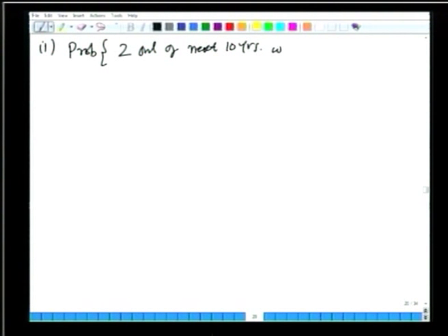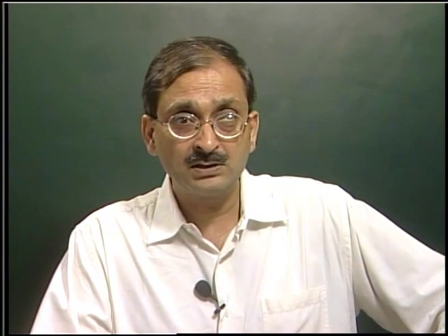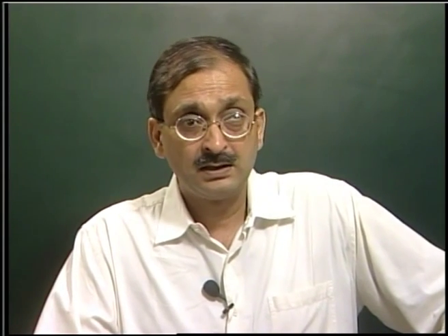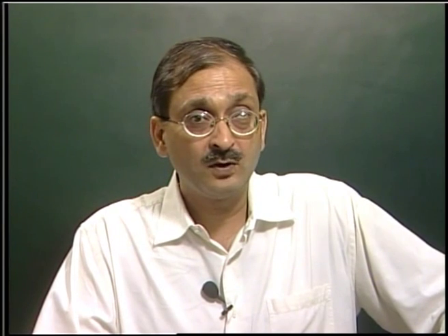will have, I will use the short form here, the March runoff greater than or equal to 4 centimeters, right. That is what we have to find in the first part. What will that be? That will be nothing but P 2, 10, isn't it? All right. So, what is this? This is saying that we have to find the probability of occurrence of the March runoff being greater than or equal to 4 centimeters exactly twice in 10 trials or in next 10 years. That is what we are saying, okay.